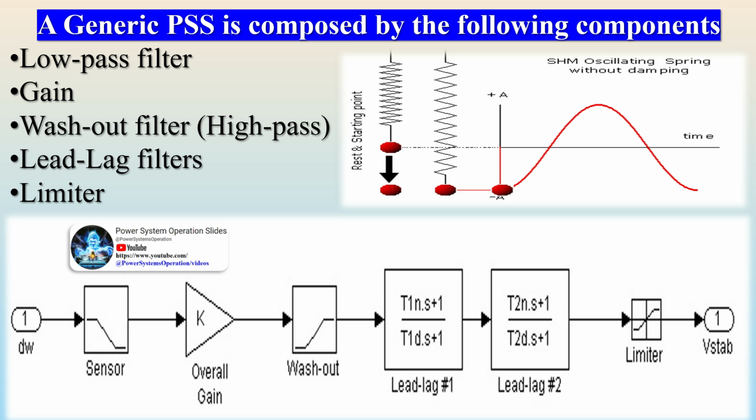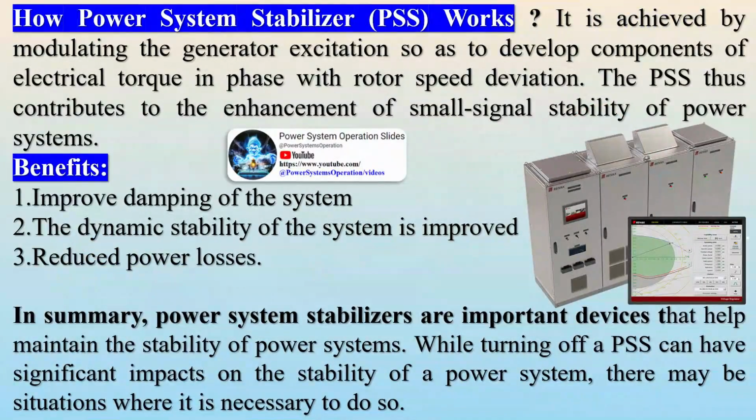The frequency response of the system under load can be used to tune the PSS. After tuning the PSS, the frequency response of the PSS can be measured and compared with expected models before being added to the power system.